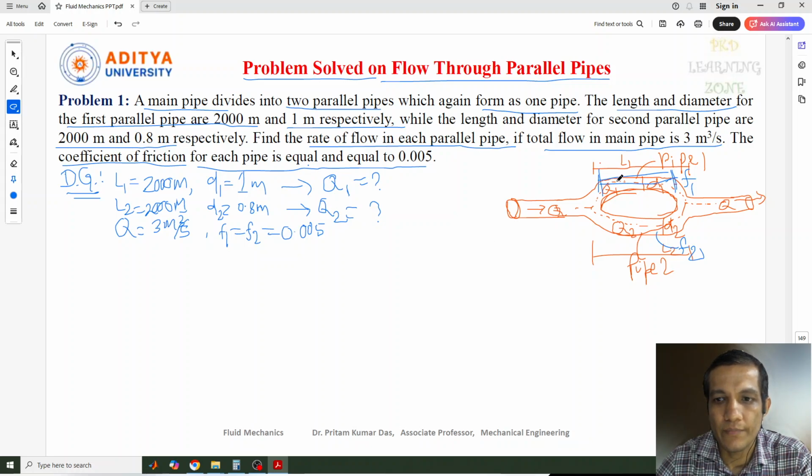So for this, the losses, or the head loss, of the fluid which is flowing through a pipe. The loss of energy due to the major loss, that is due to the friction. For that we have already derived previously. So we got the equation, that is nothing but we can write 4fLV square by 2dg.